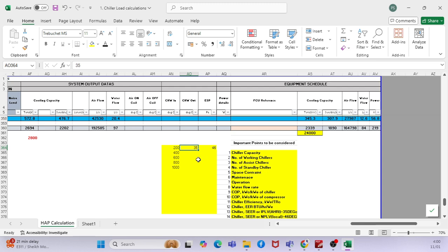So you have some other options when you go below 35 degrees Celsius. That is also an important reason why they test the chiller at 35 degrees Celsius. The higher you go, the more you need cooling, but the lower you go, you may not require a chiller. You may require some other type of system, like an adiabatic cooler. That is an important point to be noticed.